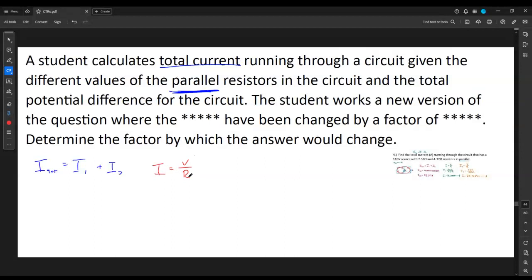Dividing those two will tell us eventually what that thing does. Now here, I didn't put any subscripts on this, because this is just in general. It's taking Ohm's law and solving it first. But we can take this information and plug it back into here, and we can use this for any individual current in this parallel circuit.